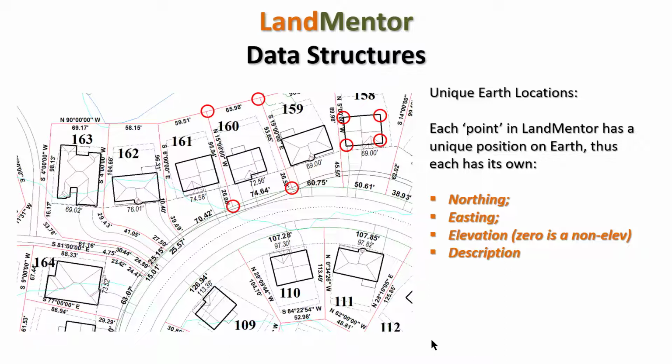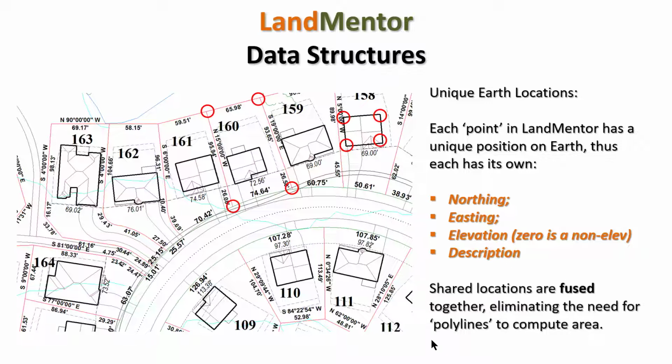Every point has a description. Well, how did it get the description? You don't want to put descriptions all day long. Well, the surveyor will have descriptions, but let's say you wanted to stake out all the building corners. Well, the building layer is attached to the points, so it automatically describes those points as buildings. So it populates the different information, and then you could stake out your building corners, your center line, whatever you want to stake out, you could download to the data collector. It makes surveying a lot easier, and it makes really everything easier.